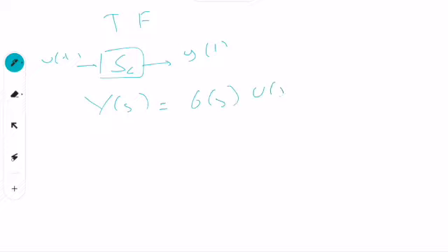Okay, so the transfer function for continuous time systems is this. So we have a system. This is y(t), this is u(t). If you can write Y(s), which is the Laplace transform of y, in the form of this, then we call this the transfer function. As you can see, it simplifies the behavior a lot. In order to find the output, if you know the Laplace transform of u, just a simple multiplication, G times U gives the output. This is linear time invariant.